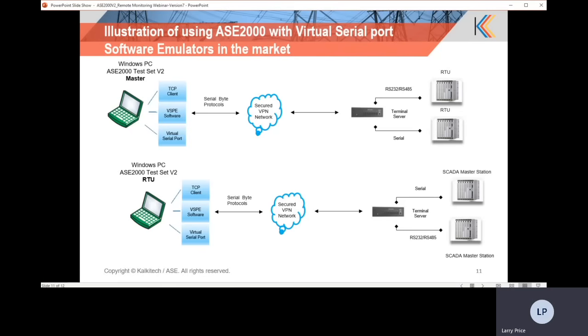Port settings such as baud rate, parity, and flow control are adjustable on the virtual COM port. Connectivity occurs using TCP/IP with a terminal server. Serial information is encapsulated in a TCP/IP frame and transferred to the terminal server's targeted port. Serial data is processed to and from a terminal server connected to a field-side device on the network with a PC running ASE2000.